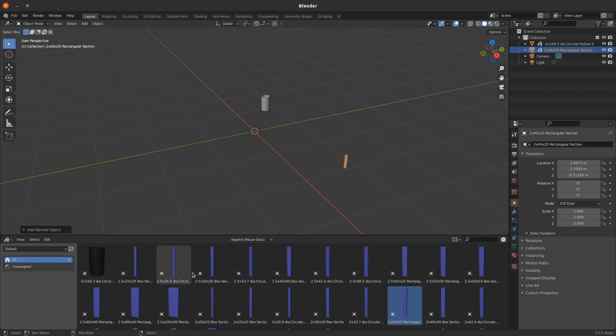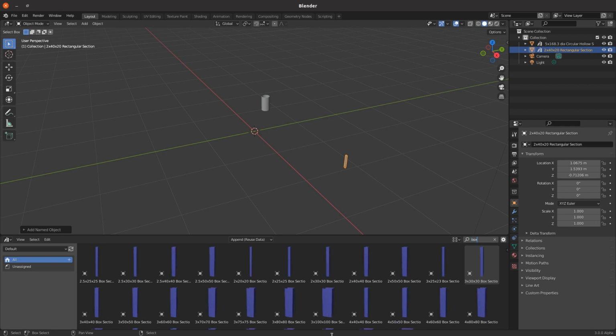If you want to refine what you're looking for, if you're looking for box section steel, you can just use the filter function under search and type in box, and that narrows it down to just the steel type. I think that shows that Blender's asset browser that's being developed is going to be a real asset for Blender, not just for storing libraries of parts. It will revolutionise the way models can be built from existing meshes that you've built into a library if you think they'll be useful in the future.